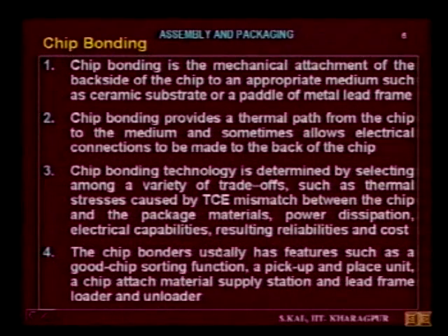Now, chip bonders usually have features such as a good chip sorting function, a pickup and place unit, a chip attach material supply station, and a lead frame loader and unloader. Why are those features necessary? Because on a wafer there are a large number of chips. Out of those chips, it may be possible that a few will malfunction.